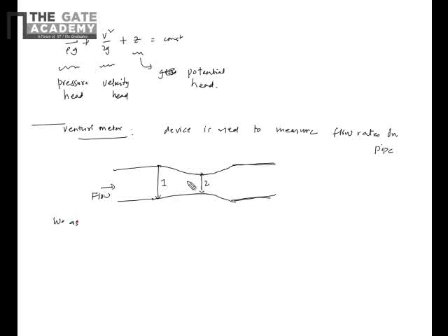So we assume that the flow is ideal, and we can apply Bernoulli's equation. So p1/ρg, it's at the same height, so the z term will not come, is equal to p2/ρg plus v2²/2g. Now these areas of cross section, I know this is A1, this is A2. So the volume flow rate we already saw in terms of area of cross section is constant. A1 V1 is equal to A2 V2. So what I will do is I can represent V1. Okay, so velocity V2 is more.